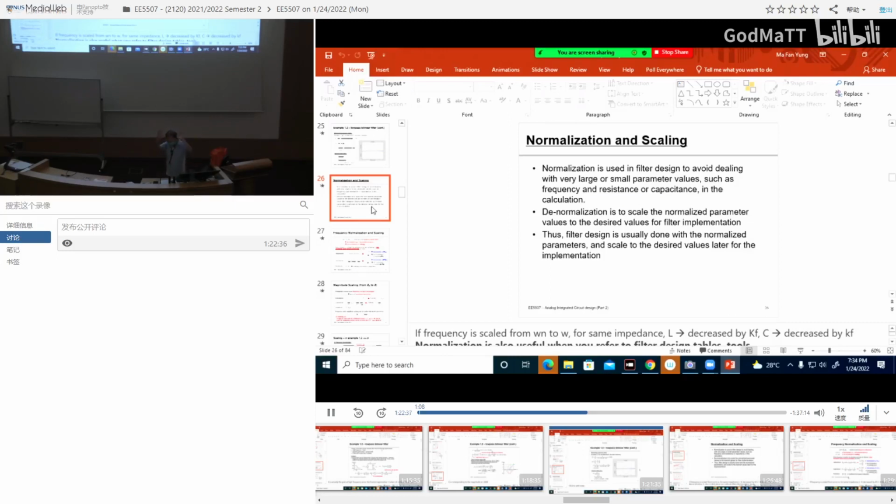Basically, very important for this bilinear and for all these filter topics, please make sure you understand all these transfer functions in the Laplace domain. How to manipulate them, how to get the DC gain and DC phase: put S equals 0 or omega equals 0. At high frequency, how to find out: S equals infinity or omega equals infinity.